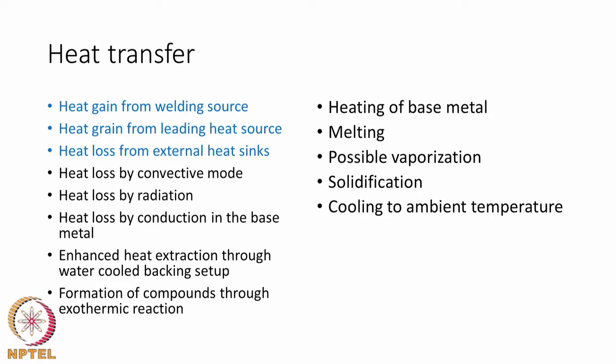Heat transfer to a weld will be basically from a heat source, from the welding source, and then we also have an additional heat source sometimes, with a leading heat source, that is, in front of the welding torch we may have another torch which gives a preheating locally, which can be, for example, in tandem.